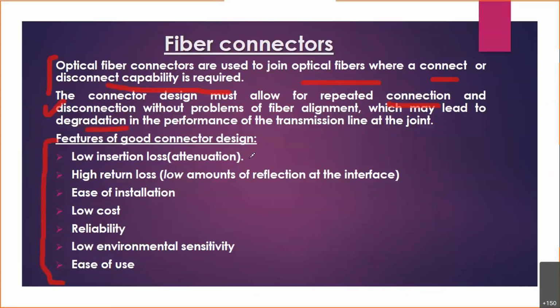First, low insertion loss, that means less attenuation. So it has to be minimum. When you incident the signal through the connectors, there itself the losses have to be very less. That means from there you have to design connectors such that if you supply 100% input at one end, the other end transmits almost 100%. So insertion loss has to be minimum.